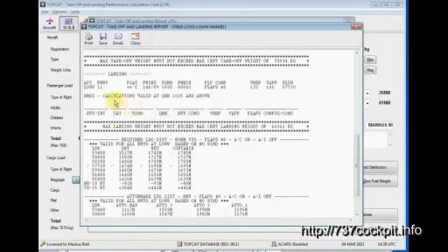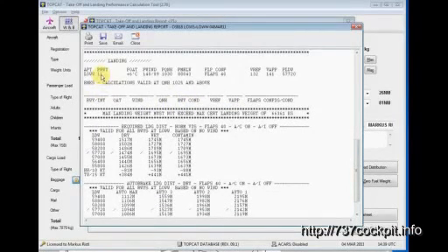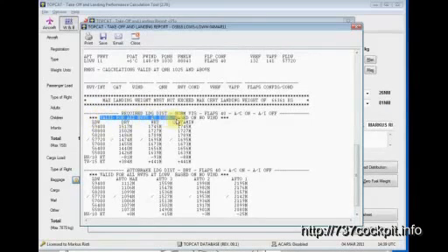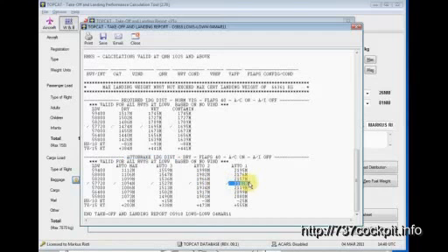Below we have the landing configuration, landing runway 11 here. We have there valid for all runways in Vienna based on no winds. So we would have a calculated landing weight of 57.7 tons for a dry runway. If we land with auto brake 1, we would need 2,142 meters. With auto brake 2, 1,953. With auto brake 3, 1,527 meters. And with auto brake maximum, we would have a landing distance need of nearly 1,000 meters.